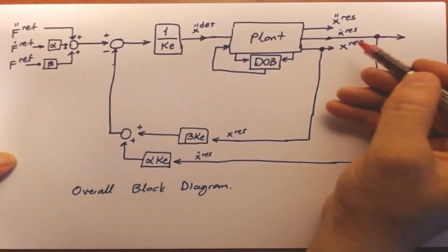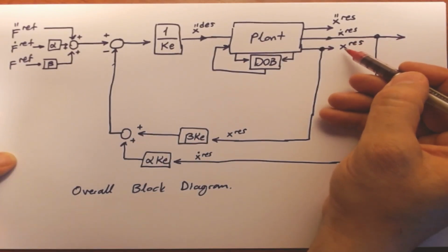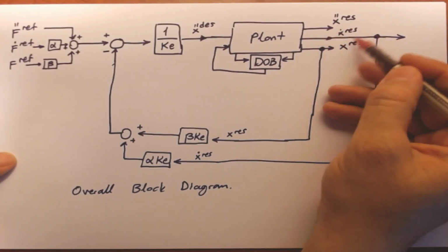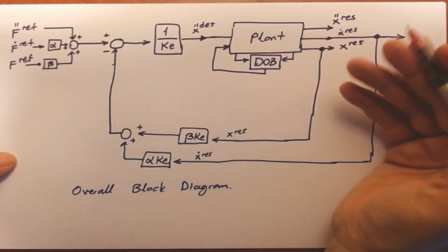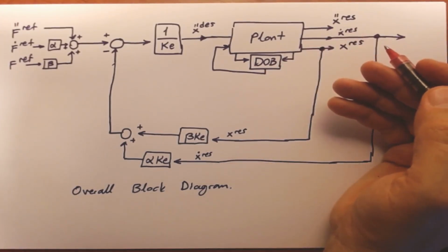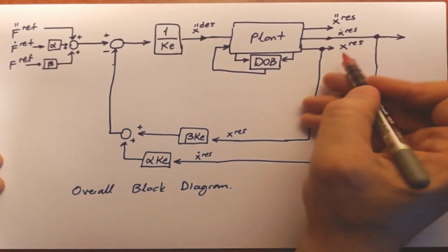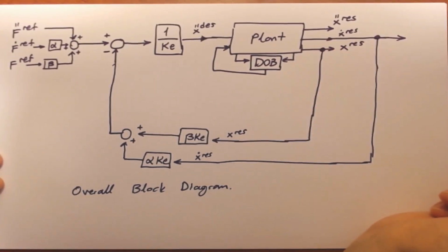Well, let's start with the simplest one. It's easy to take the response measurement from a plant through an encoder. That's the easy part. The response velocity of the plant, that's the response speed of your motor actually, is easy to calculate once you have the response position from your plant.